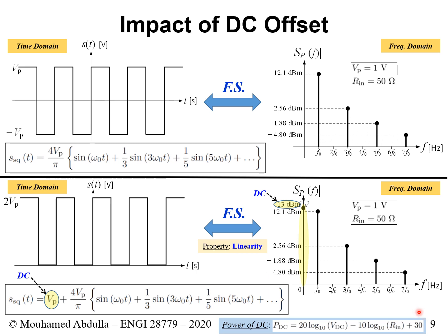Right? Remember, we had the square root of 2 for sinusoidals. Here we don't have this. We don't do the RMS. Okay. So just be very careful with this. Sometimes I even notice these mistakes in some books. So they make the mistake of not determining the DC component correctly. Okay, that's pretty much it. So these are kind of the big things that I wanted to mention on this slide.